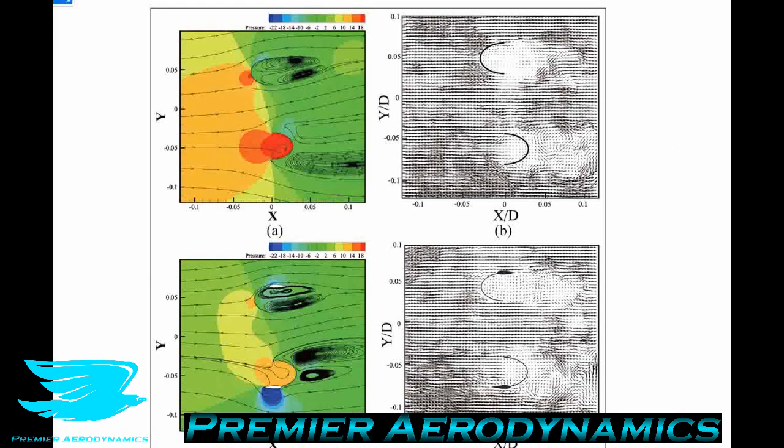One major difference between the drag producing blades and the blades that produce both lift and drag is that for the blade on the left side of the axis, so this one here and that one down there, the airfoil is effectively pointing downstream, and we see very low pressure on the outside surface of the airfoil. So just here we see very low pressure, whereas here there's no low pressure zone. We don't get that low pressure zone for this drag only blade,